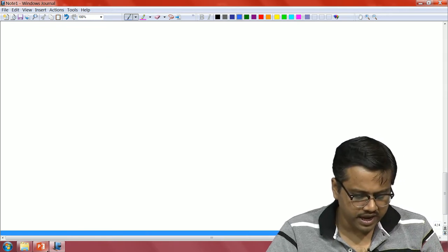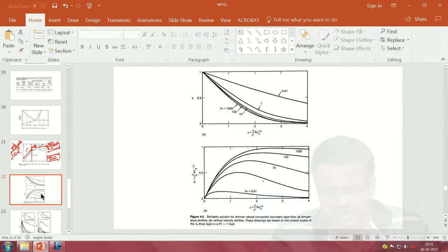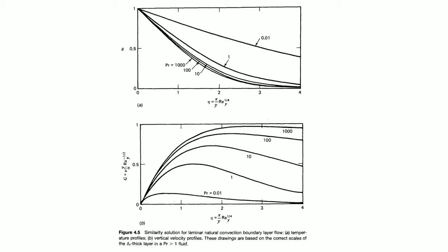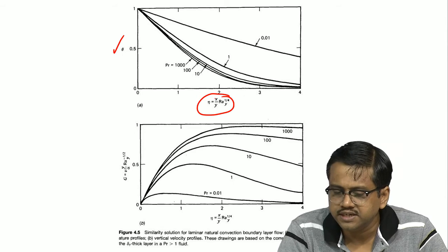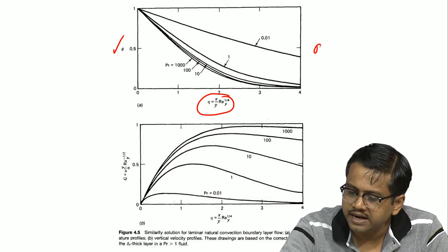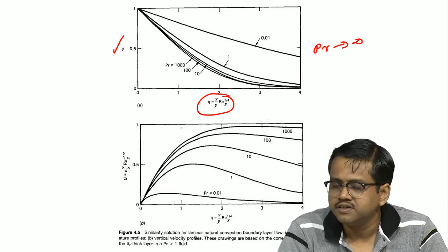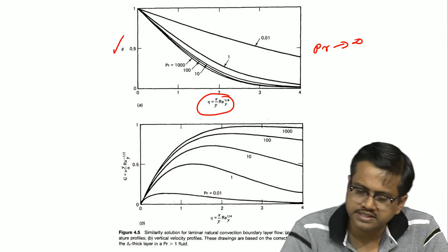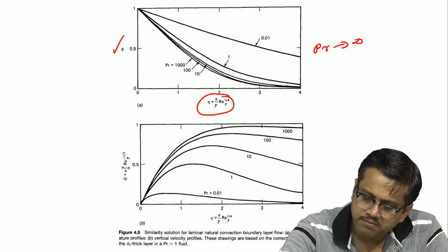Okay. So, let us look at what we get out of this, right. So, after the solution, this is what we would get, for our Prandtl numbers, I mean you see the whole expression for all types of Prandtl numbers, we have exactly plotted it. So, the first one is basically theta, plotted against the similarity variable which is eta, right. A couple of key things that you see immediately, that as Prandtl number goes to infinity, or becomes very high, you can see that all these theta curves kind of merge with each other.